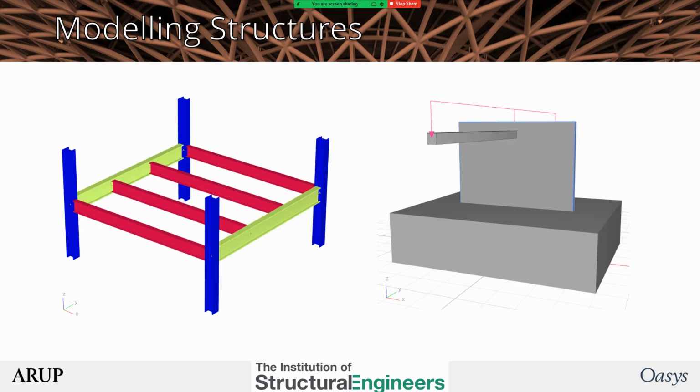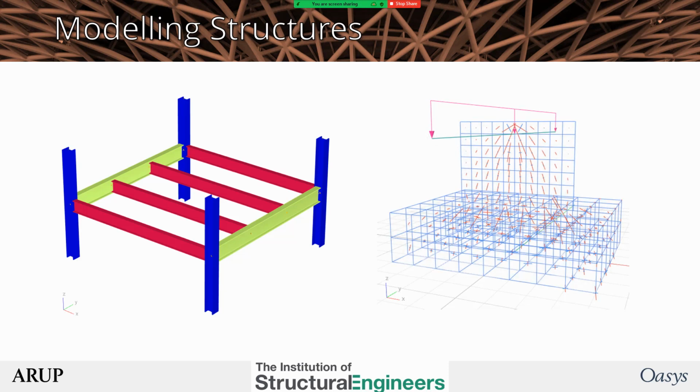Now, FE models are analogues of the real structure. And we model them with 1D, 2D, and sometimes 3D elements. Now, 1D elements are great when the stress flows are essentially one-dimensional, like in beams. The one dimension, the length, is considerably more than the other two. 2D elements are suitable when the stresses move in 2 directions, one dimension, thickness, being considerably less than the other two. And 3D elements, well, I need to guess about that.